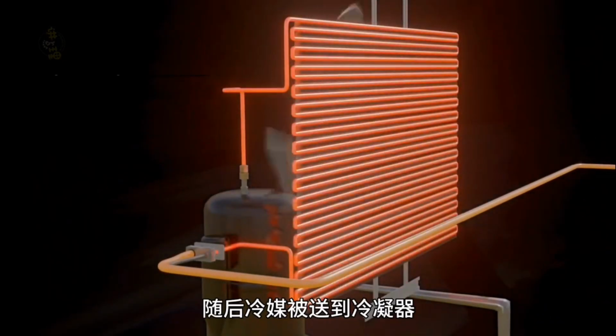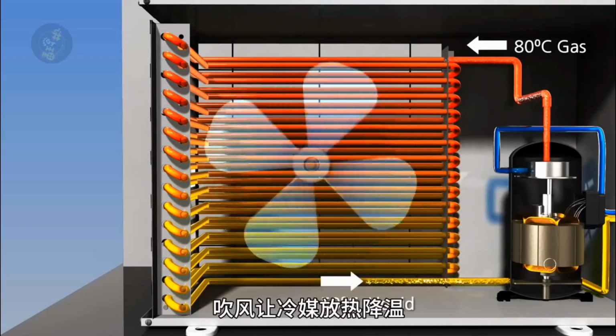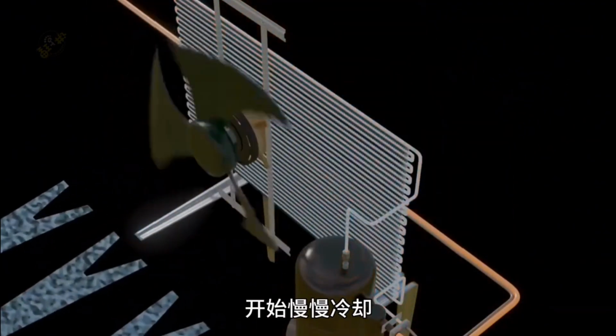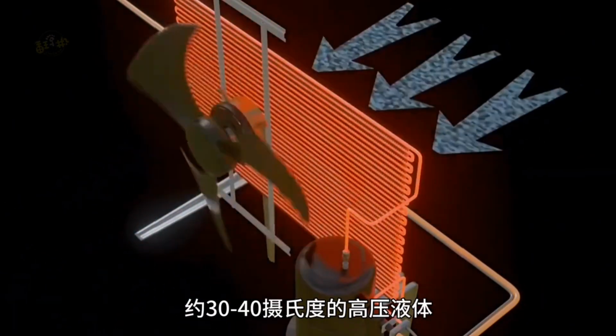After the compressor compresses the refrigerant into a high-pressure, high-temperature gas, the compressor's task is complete. The refrigerant is then sent to the condenser. The condenser is like a row of densely packed heat dissipation fins, with a fan blowing air over them, allowing the refrigerant to release heat and cool down. This causes the refrigerant gas, which is around 100 degrees Celsius, to slowly cool and gradually condense into a high-pressure liquid at a temperature of about 30 to 40 degrees Celsius.